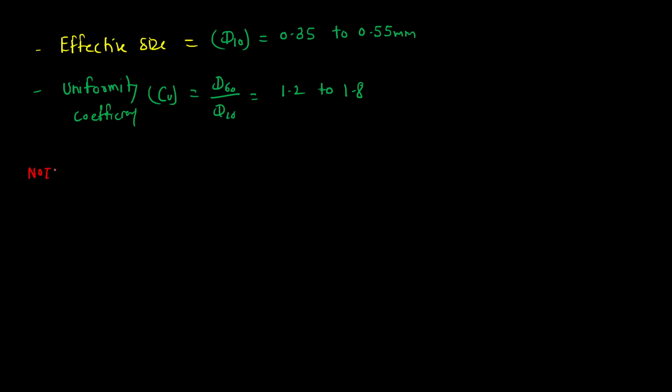In slow sand filter, if you remember, only the topmost part, that is topmost filter media of sand, is washed. Why is it only washed? Why is the gravel bed not washed? Because the topmost sand only plays an important role in the cleaning process. But in case of a rapid sand filter, the entire filter media and the gravel box both play an important role.